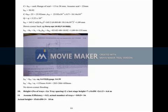Phi is the fraction, phi E is equal to HL by HF. HL is the height of the liquid and HF is the total height. That is, you are maintaining 40 mm, the weir height. So using the formula, phi E you are getting 0.44.